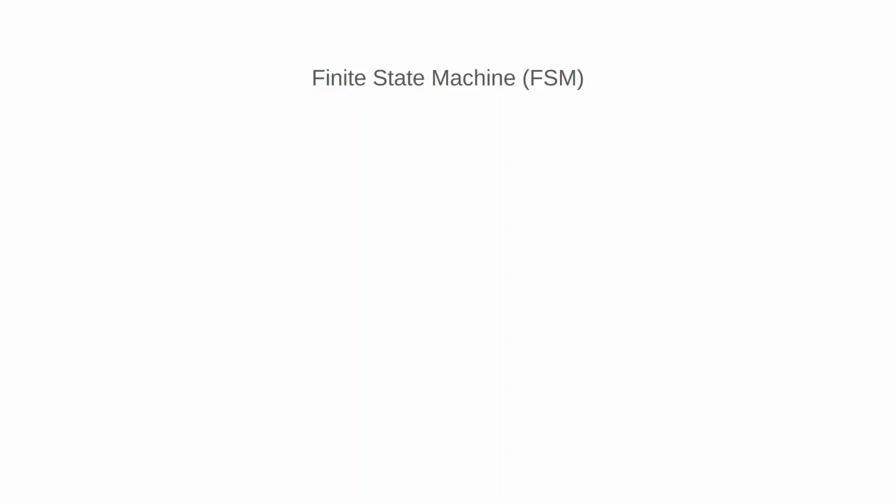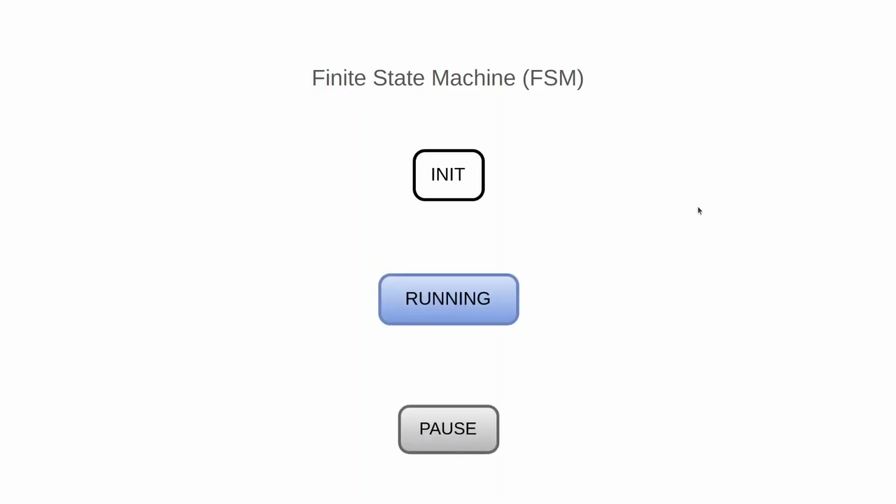A finite state machine is a technique of building applications. In that technique, you provide the states for your application and you provide some way to transition between different states. We can define states for our Microbit Pomodoro project, and we need only 3 states for now. Later, maybe we will expand on this. Init state is the first one.